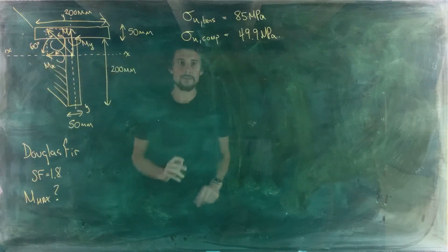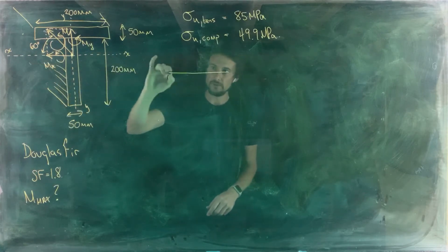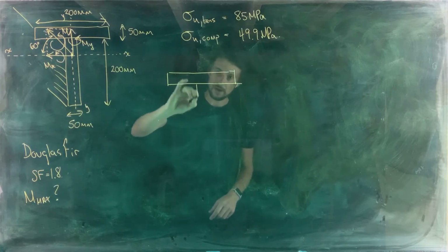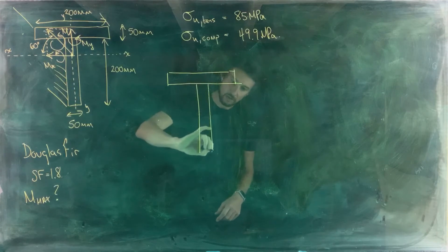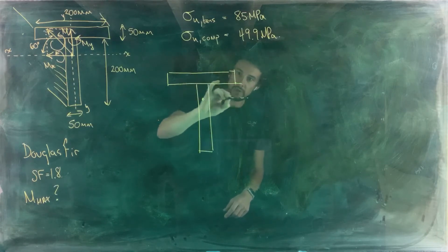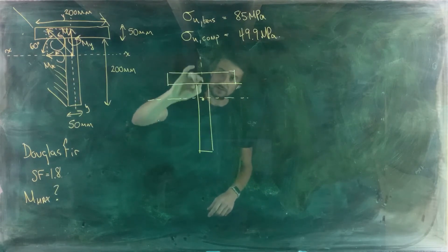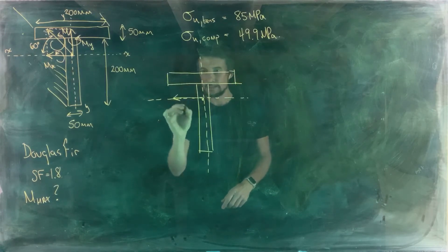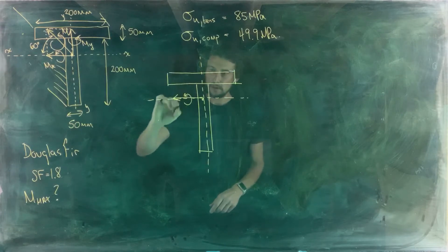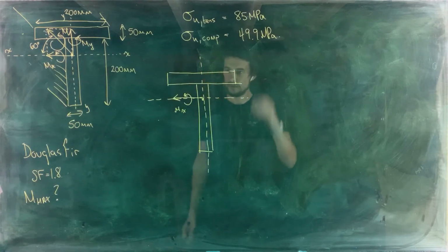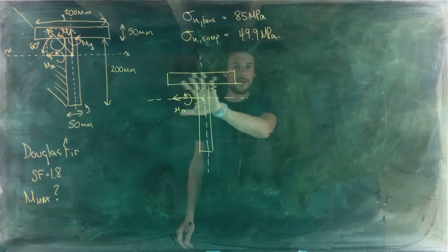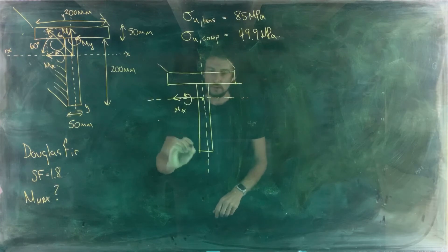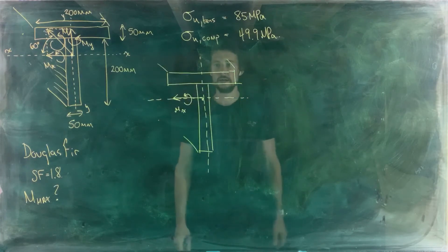Now I'm just going to grab this and redraw it just so that there's not something that's all cluttered by these dimensions, so I can do a bit of annotation for you, showing where compressive and tensile stresses are going to be maximum. So I've got M subscript X this way. Okay, I'm going to think about Mx first. Right, whole beam is going into the plane of the glass here.